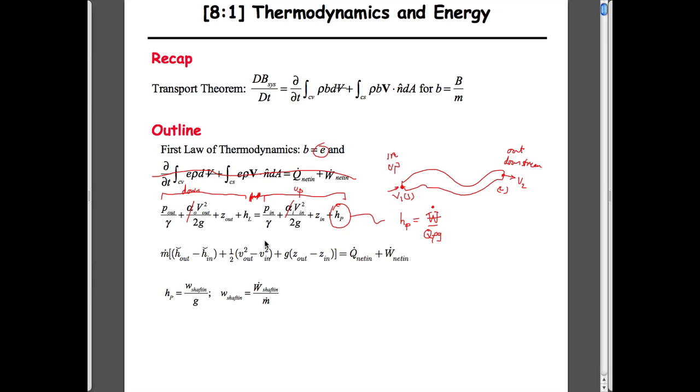As we'll deal with later, when we talk about head losses, they are always positive. It's the trick of pulling a briefcase across the table: pull it one way to get it to one place, you dissipate energy. You pull it back to its resting place, you don't regain that energy, but you lose an equal amount again. So head losses are always positive. I can't think of any condition when they wouldn't be. So that's the one expression that we have, which we've used for pipe flow as well.